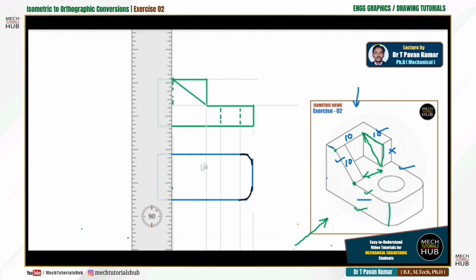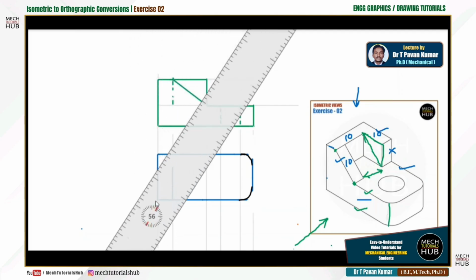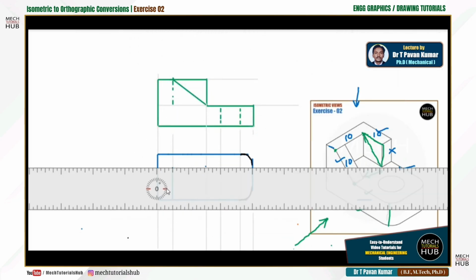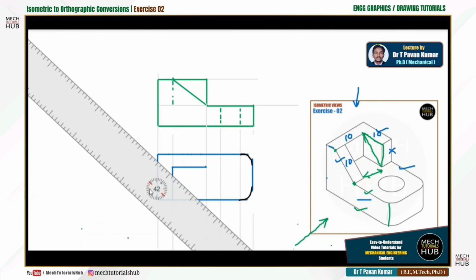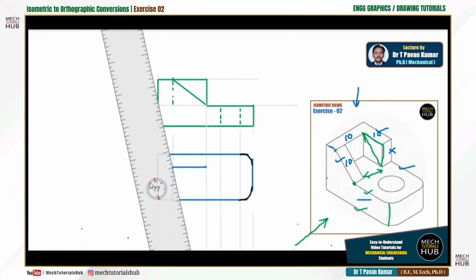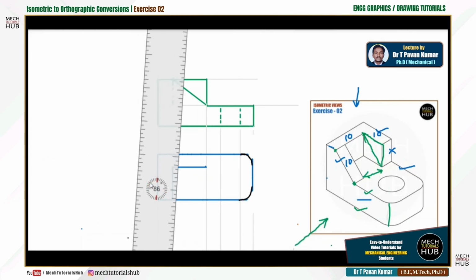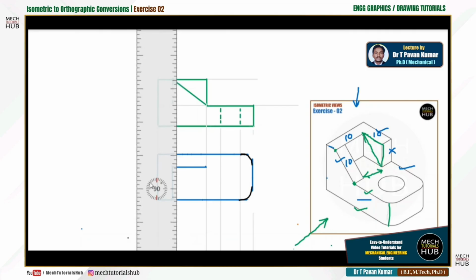Okay, now draw a horizontal from here to this point and rotate the drafter scale to 0 degrees and align with the dimensions already marked and draw horizontal. You got it. Then again rotate the scale to 0. Now these construction lines which I have drawn with 2H pencil, light color, will help you to connect.